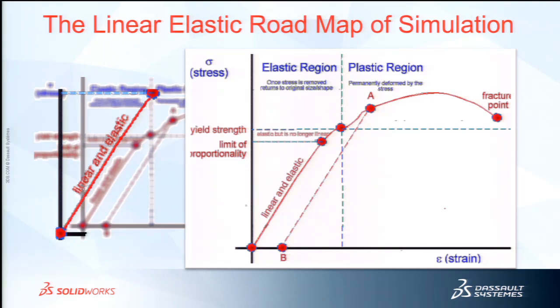But if you look, we're at point B now, right? The path it took was from A to B to go back down to the bottom after we took the loading off it. It didn't make it home to its initial point, right? It landed at B, so it's a different place. The intensity was so severe it changed the way the model behaved. And that's not what we want to do as designers.